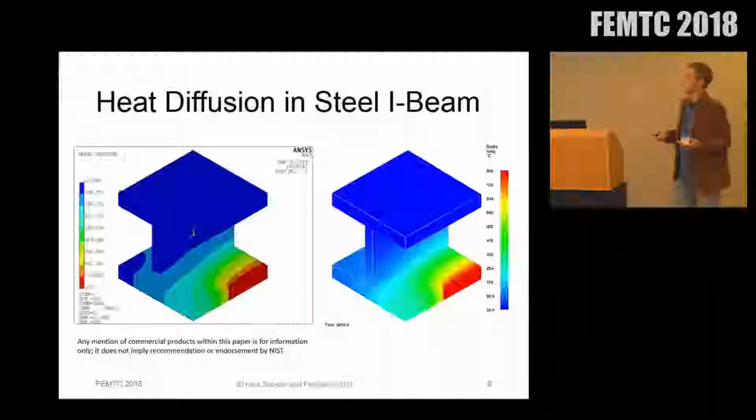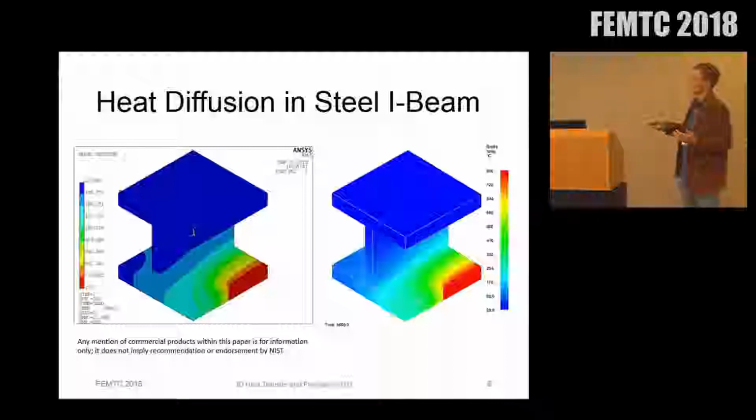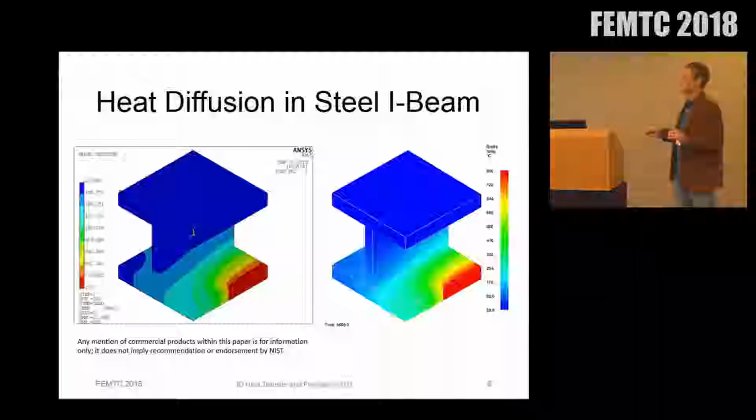So let's look at a quick example. This is something that Chao Zhang put together. Of course, this is not an endorsement of ANSYS by NIST, but he used ANSYS, which is a finite element code. What he did is, this is just steel. I believe this is about 10 centimeters or something across here. He's got a hot patch that he holds at 800 degrees on this face, and I think the case runs for something like an hour, 3,600 seconds.